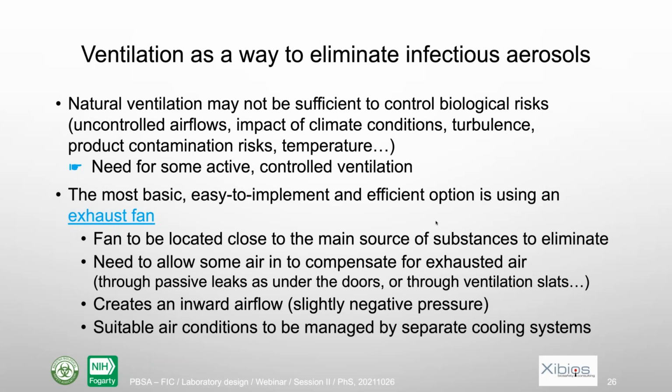Why? Because with natural ventilation, we have non-controlled airflows. So people could be exposed in case there would be an accidental aerosol, for instance. And also because of the impact of climate conditions, like air turbulence and so on the people, but also on product contamination and so on. So most of the time in a biosafety lab, you will need some active controlled ventilation.